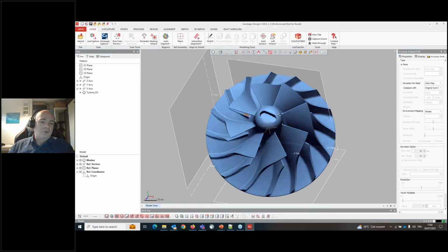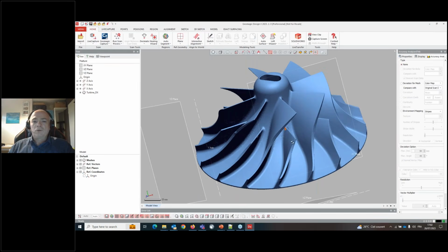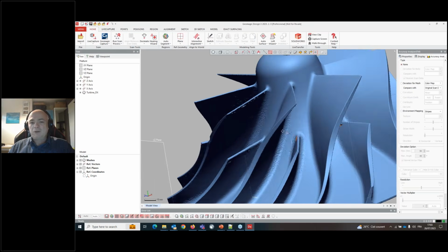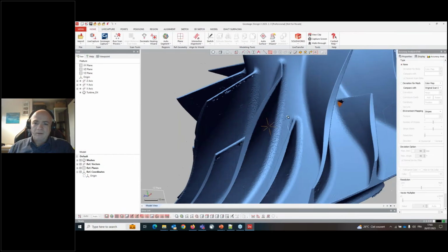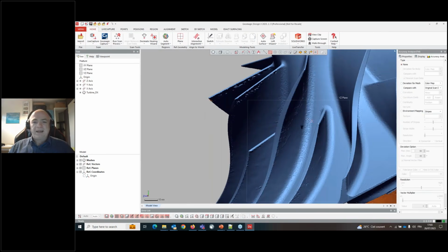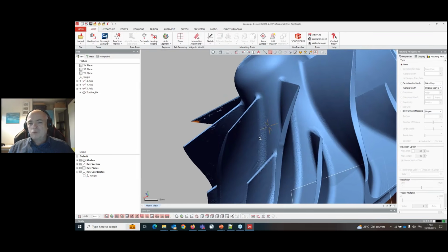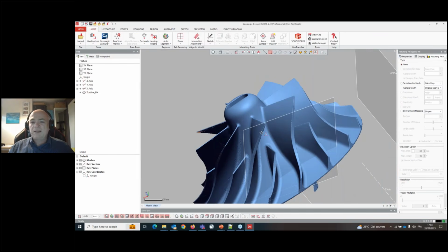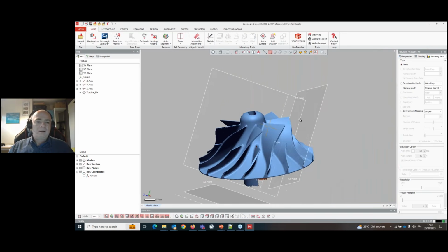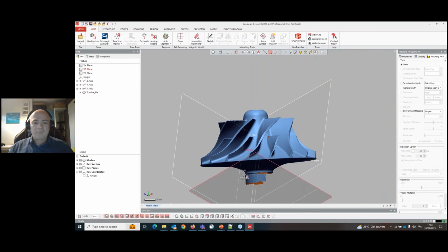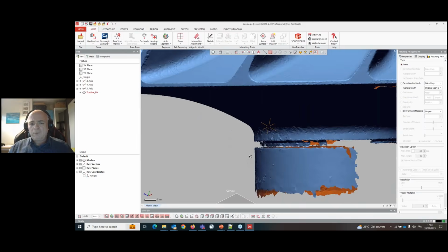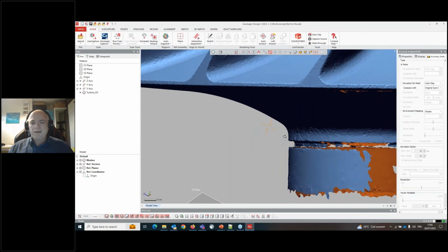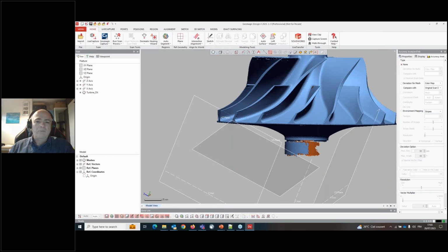It can also be a cloud or whatever, but here it is just an STL file. And first of all, when you get the file, you try to look at the points and look at the definition, or if there is any problem in the file. You can see that the scan has some problems, some holes, because this is a real scan. We just have to take that into account when we make the process of reverse engineering of that part. You can also see here that I have a groove. It's not really nicely scanned, so we'll take that into account in the process.